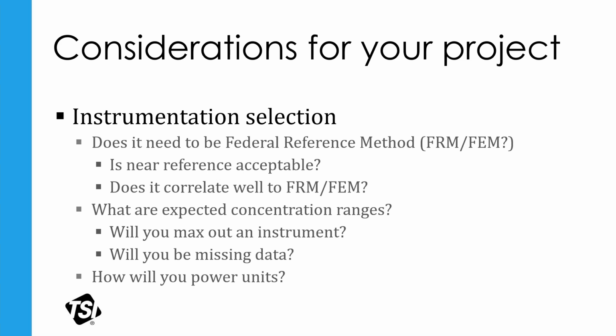Some can handle very high concentrations very well. Others are really made almost like for ambient air monitoring, not really made to be put in a really dusty or dirty area. So think about that, because there's the possibility you could miss data if you max out an instrument. You might miss some points that you may need to collect.